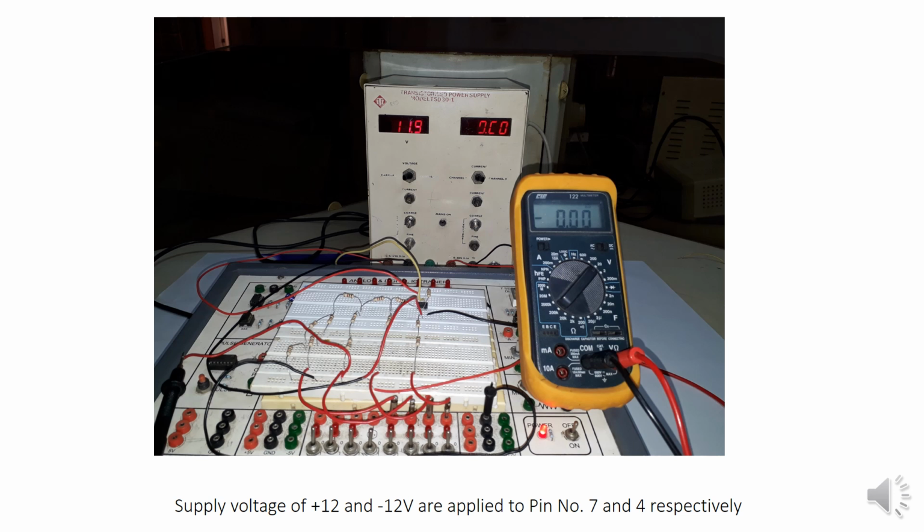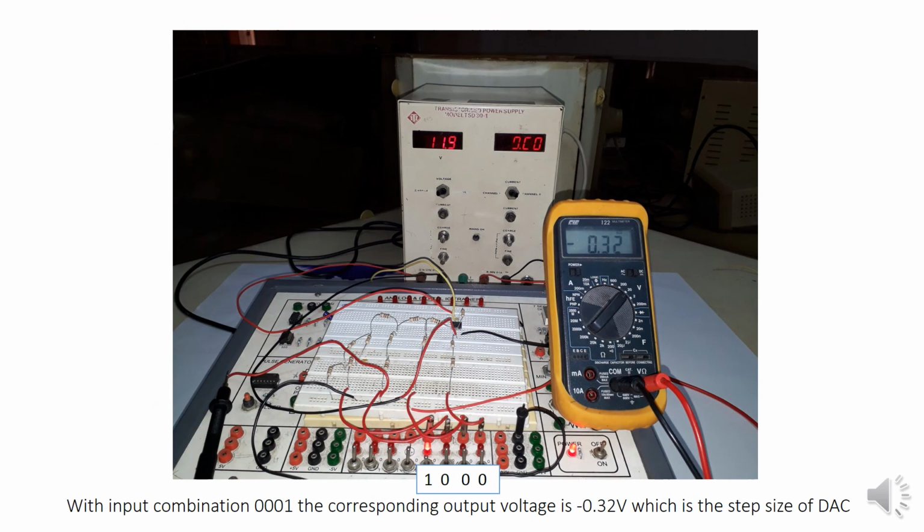Now you can see the input is 0, 0, 0, 0, all zeros. That means all are connected to ground, hence the output is 0. Now let us make LSB as 1. Whenever we make LSB 1 and the remaining 0, the output is minus 0.32. Minus is because it is connected in inverting mode.